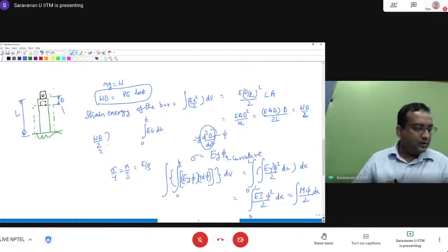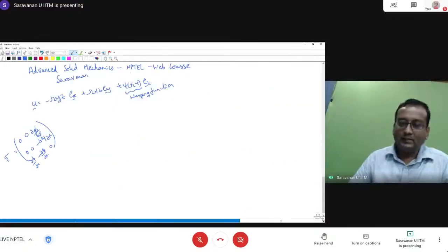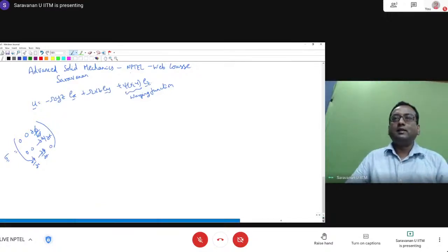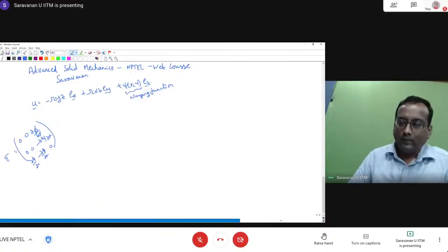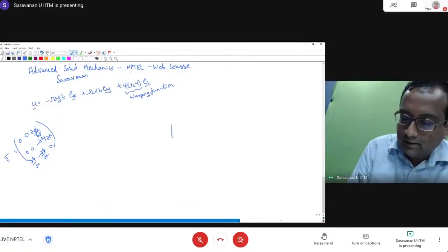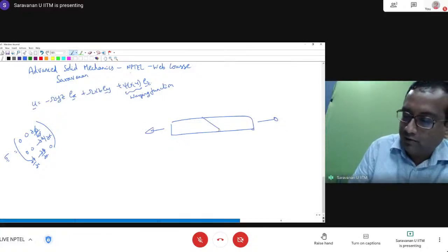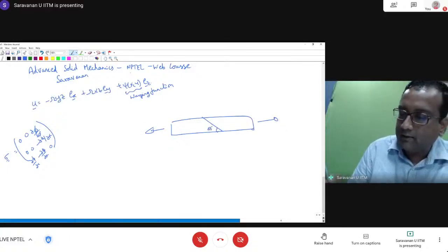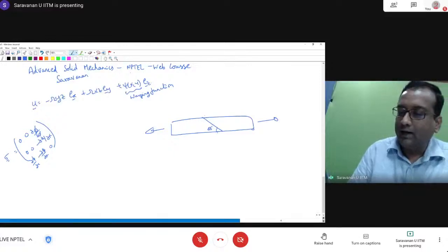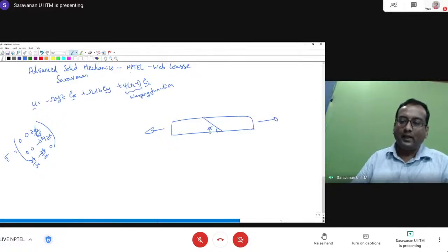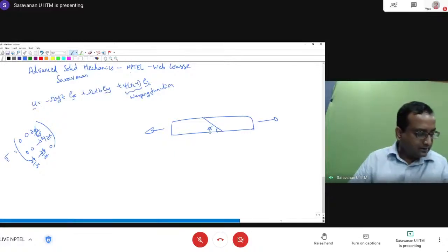Necking is not found in torsion testing, but it is found in uniaxial testing. That's because the shear stress governs the failure. Okay, in torsion, the maximum shear stress occurs in the plane of the twist. Whereas if I do a uniaxial test, where does the maximum shear stress occur? Maximum shear stress occurs at the 45-degree plane. So the metal has to slide like this, and hence it necks. Because the shear stress governs the failure, the necking happens in a uniaxial test.